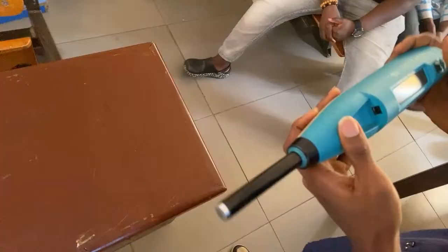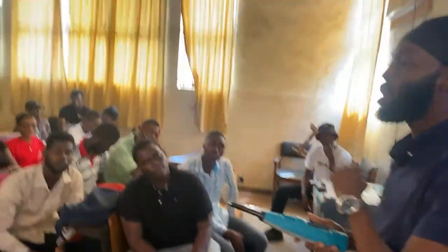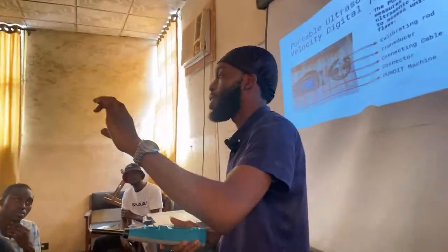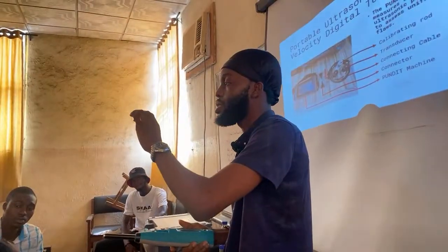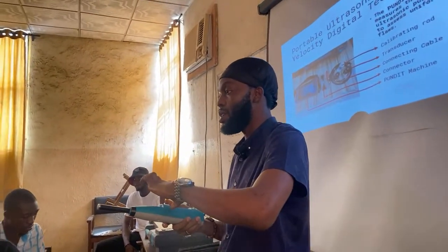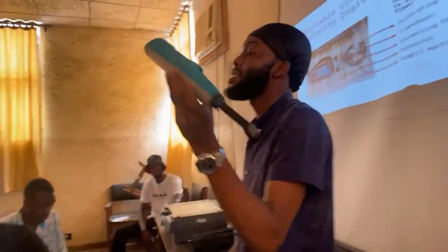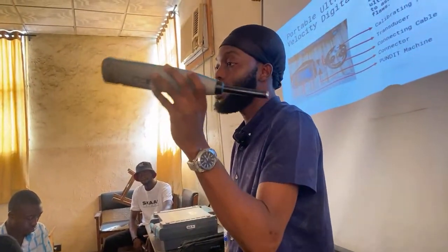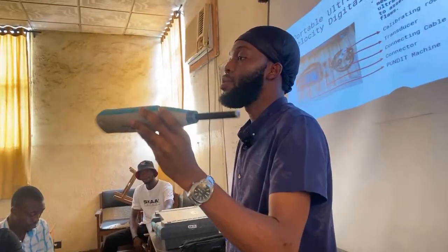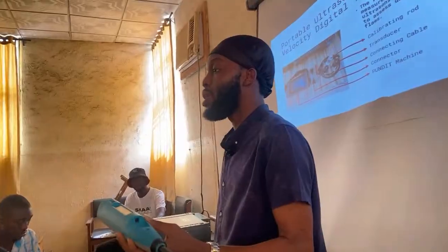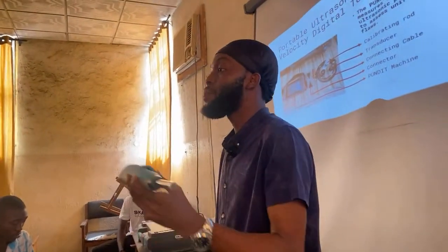After making 10 plunges or 10 shots, we check the average for it. Then it creates a rebound number and the compressive strength, which will be displayed on this LED screen. But you can do as many shots as possible on different structural elements. The thing is, you have to record the numbers, because we have the rebound number and also the impact number.